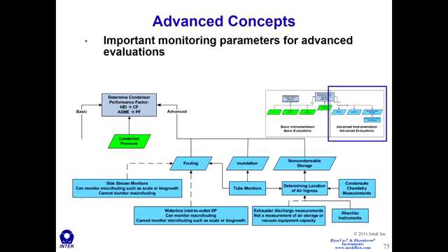Side stream monitors sample the cooling water and draw it out into a system that is outside of the condenser. Inside there, it creates a simulated environment where scaling or biogrowth is measured by mechanical or thermal sensors. Through this measurement, the potential for microfouling in the condenser tubes is inferred. So that's the instrument, the tool to monitor microfouling.